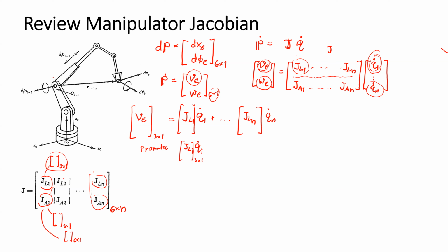So in the robot, if we consider joint i of the robot, if that joint is the prismatic joint, the z-axis of joint i will be z(i-1) by the Denavit-Hartenberg notation, and the unit vector of the prismatic joint is the unit vector that shows the direction of the z(i-1) axis.